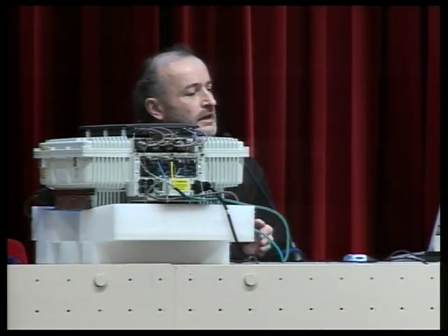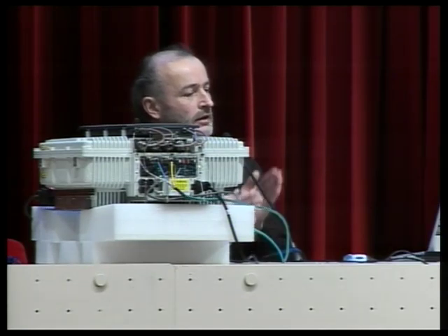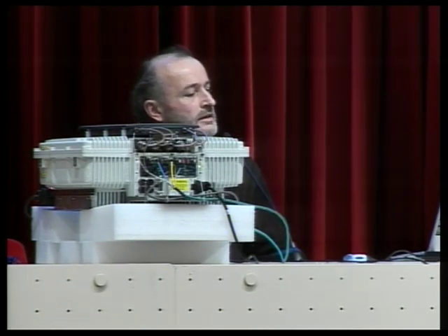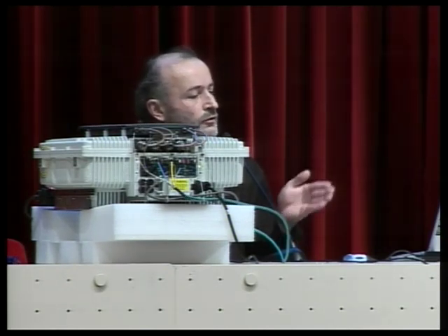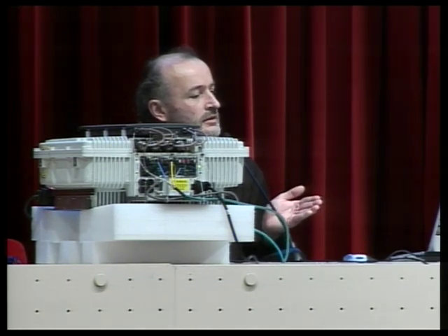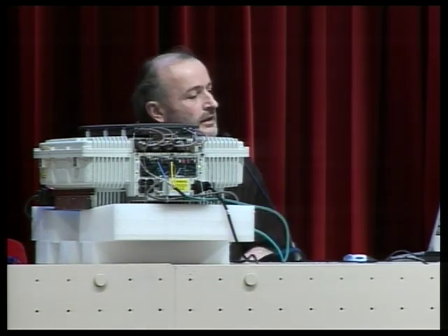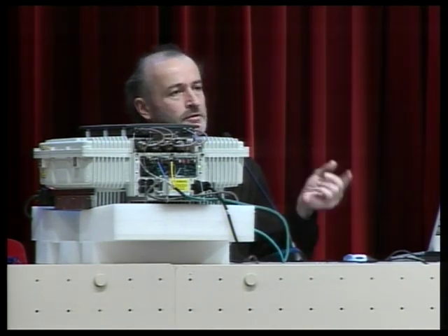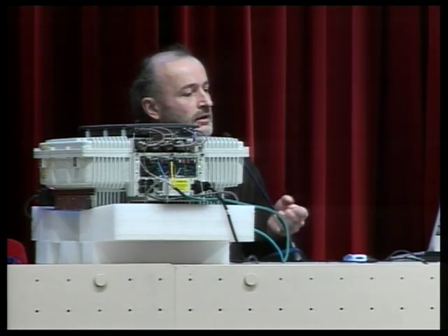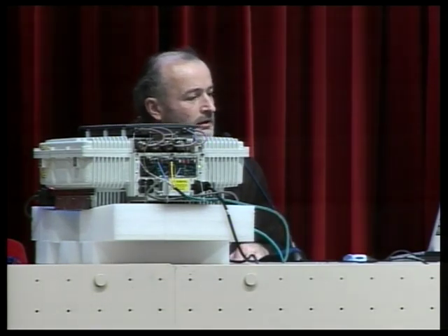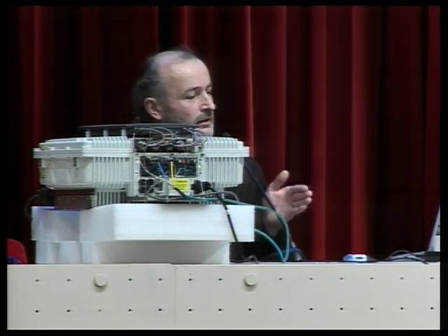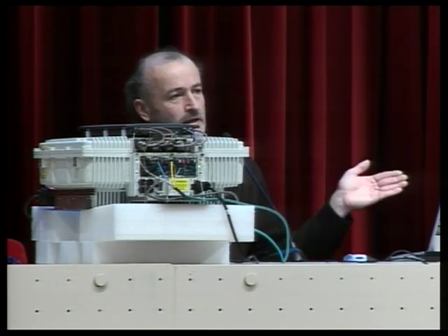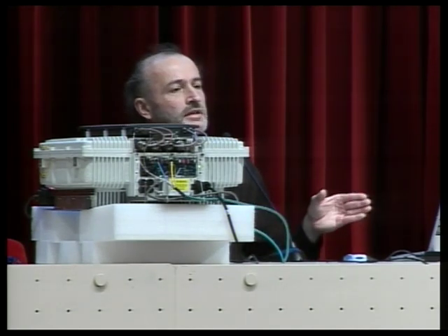The speech and data traffic is usually divided in the time slot into 4 different subslots. Basically, you don't need the full weight of 64 kilobits, so you divide it into 4 subslots with 16 kilobits each. This division is very simple. You take the first 2 bits for the first subslot, the next 2 bits for the second, and so on. This stream does not have any synchronization marks. You just have this data stream and you have to search for the synchronization by yourself.